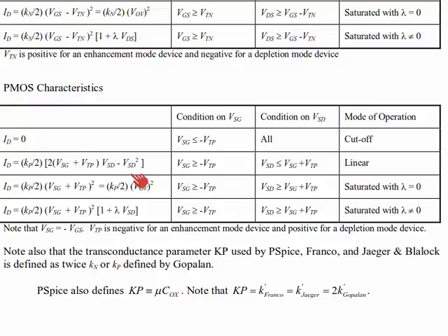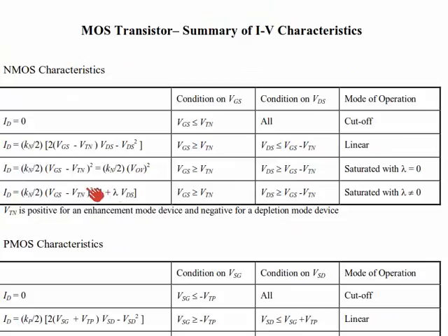Okay, now it looks like there's a fourth mode of operation here. It's not. It's just the option, sometimes, particularly when we're using SPICE, to consider that the current in saturation doesn't necessarily lie flat. It may have a slope. The slope comes from the effective channel length shrinking with drain-to-source voltage. So we have a finite slope to that line. We call that slope lambda, basically, and multiply the saturation current by a factor 1 plus lambda times VDS.